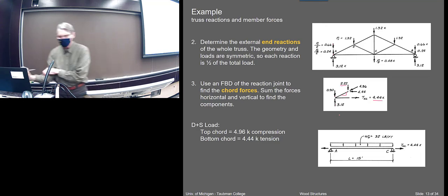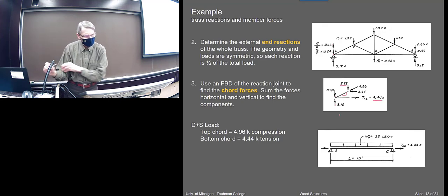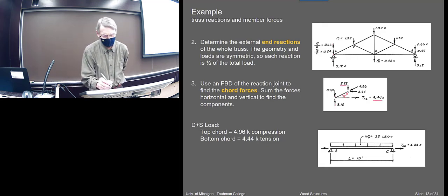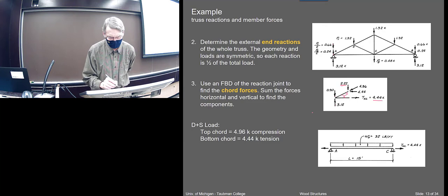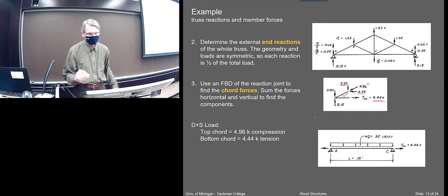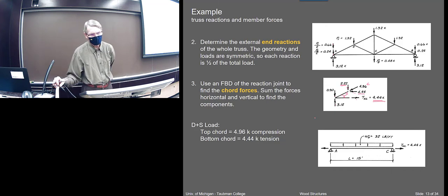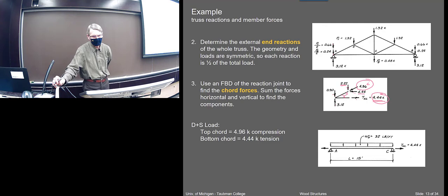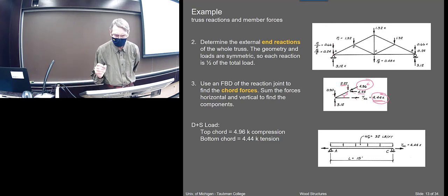I think it's 1 to 2 slope there. So if this is 222, this is 444, and these are the only two horizontals, so that gives me that force, and then the resultant of those two would be this. So that just gives me the forces from that little corner, and these are the two that I want. I want that for the tensile force, and I want that one for the compressive force. So we'll do the tension member first.